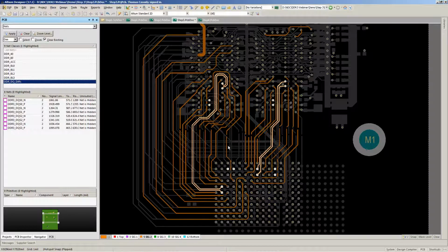Another thing I didn't mention is when the data buses, I came out here, I have all this room over here to expand into. So basically when I do the length matching, I'm going to start by pushing stuff over, and I'll route these to the length match, move these as I need to, and as you'll see in the end, I'll end up filling in all the space.